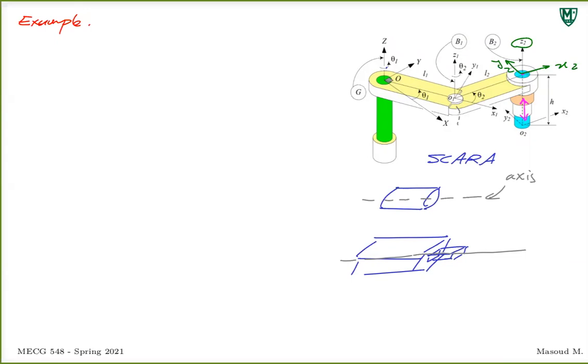For a revolute joint, you have to keep in mind the right hand rule. Your thumb is the axis of your revolute joint, or the positive direction. The forefingers show where the positive rotation is. Obviously, the opposite of that would be negative rotation. So that's what I want you to keep in mind. We'll see later on, this becomes more important.